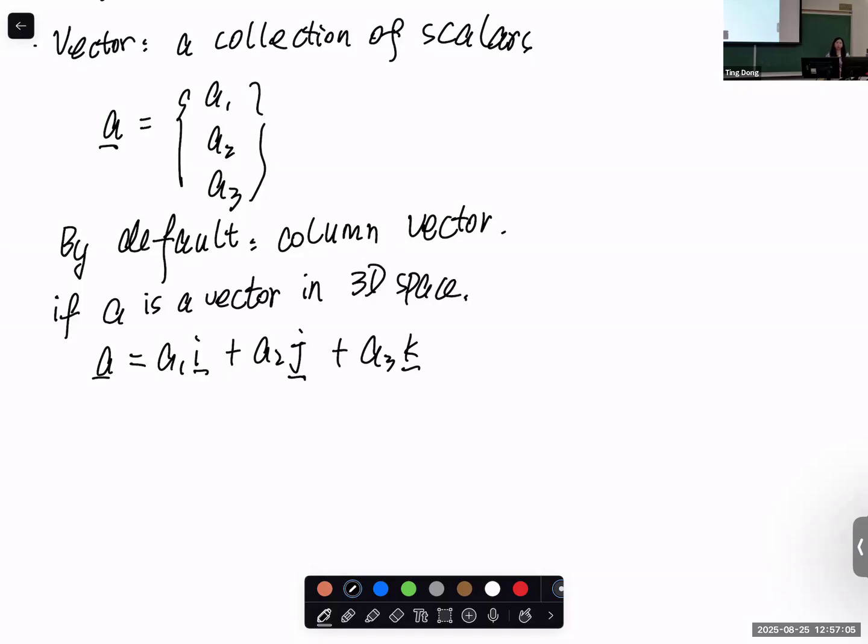And of course, you probably already learned in statics, sometimes you have a structure with force applied in X, force applied in Y, force applied in Z. Or you have a force applied in a random direction in three-space. And when you put in the force vector, K q equal to F, what you do is ask what is the component in the X direction, what component in the Y direction, and what component in the Z direction, and then it becomes the vector.